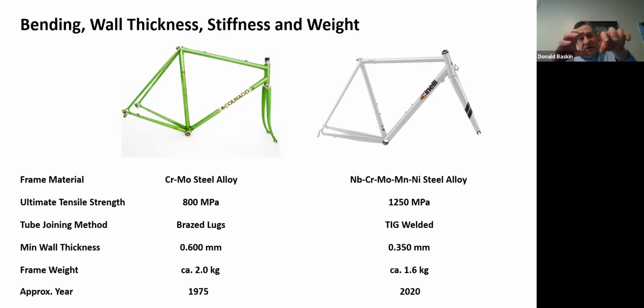And then you put tubes into it to join those tubes together, and then you braze the tubes together with a little bit of brass. You use brass because it's low temperature, and if your steel is precipitation hardened, for example, you don't want to heat it up because you might grow the precipitates, and then they wouldn't be as effective, and the material would go down in strength locally around that lug. So using brass and brazing at low temperature, or in some cases they use silver solder, you can minimize the coarsening of those grains. And now we know all about that, so you guys know exactly what I'm talking about, right?